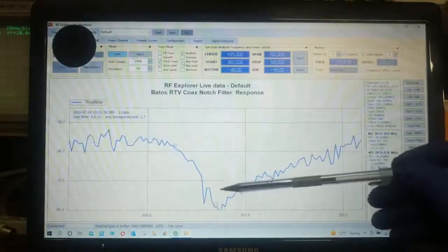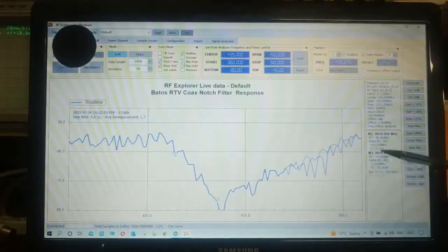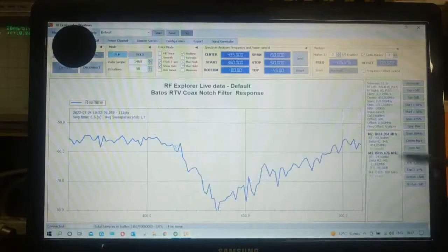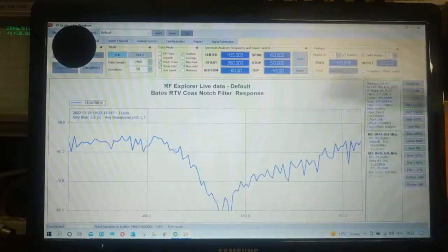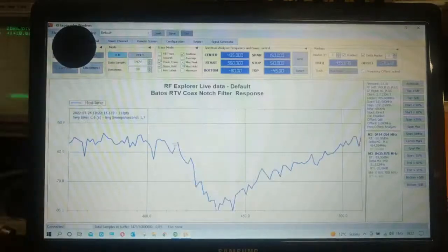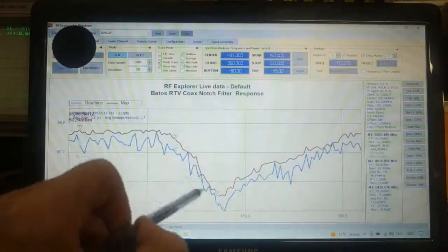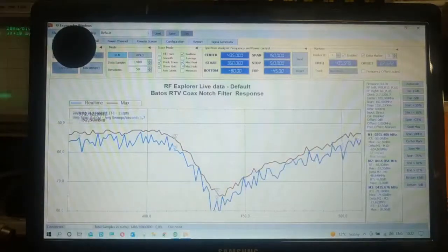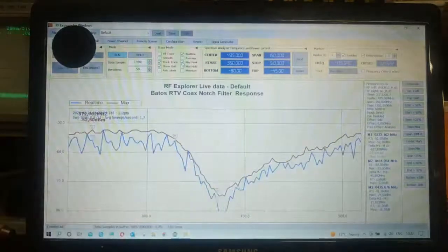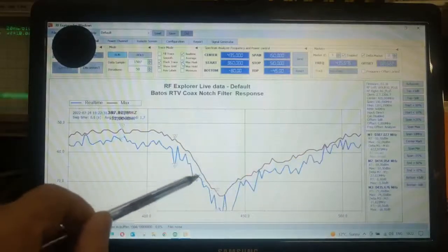If you look at it very carefully over here, number three, which is that one, it's approximately 435 megahertz, 436, 437, somewhere around there. Now I'm going to click and choose the maximum peak. I display the second trace, so wherever the real time reaches the maximum peak, it stays for a certain amount of time, and then it changes accordingly if there are any major changes in the fast sweep.